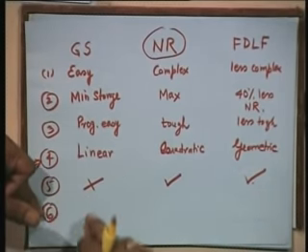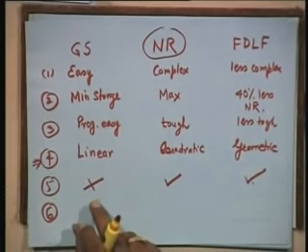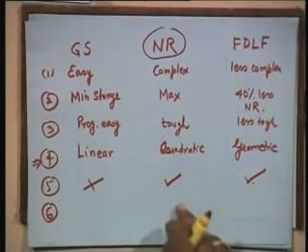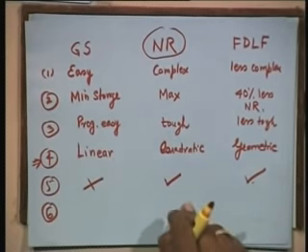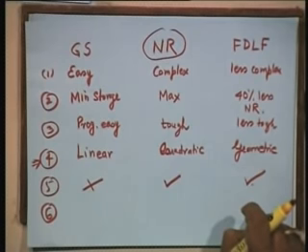If system size is small, then Gauss-Seidel is wonderful, but if it becomes a 1000 bus system, then there are problems. But this NR method does not care for system size, it can be any system size. Whereas FDLF, again system size is not that much of a problem.